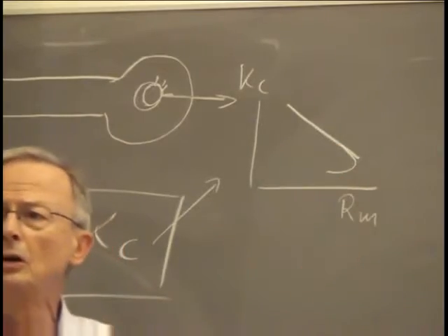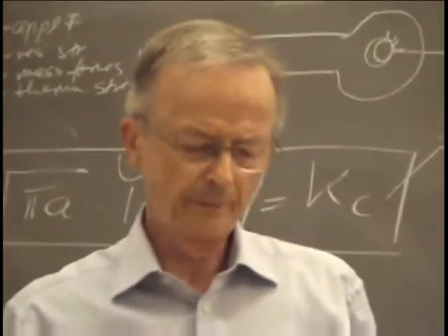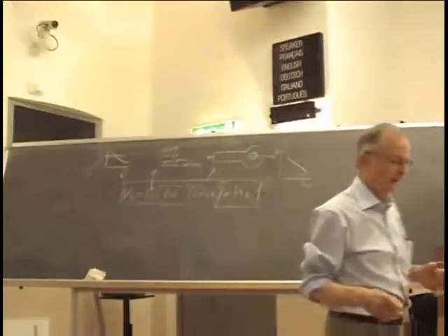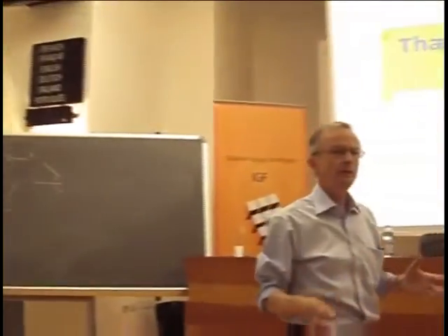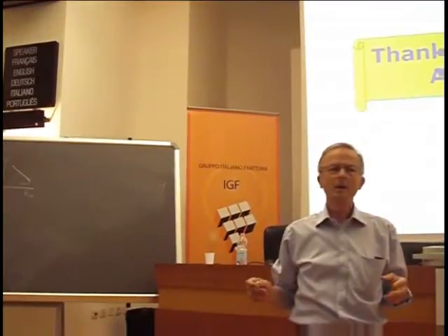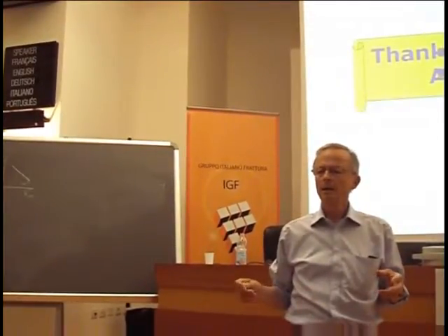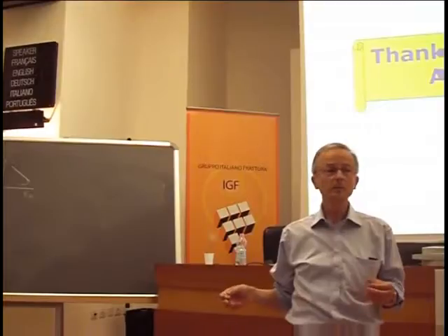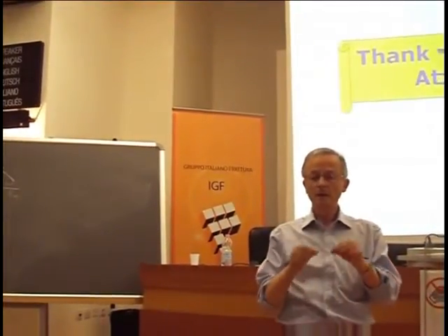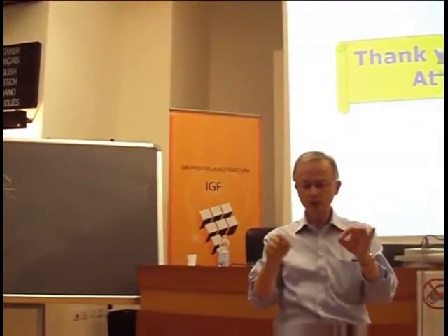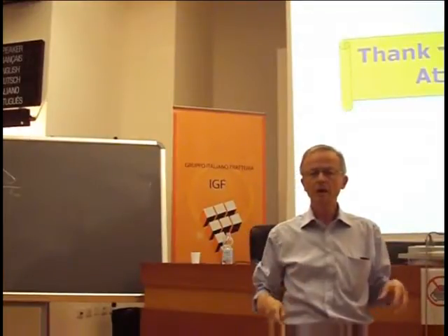No, it doesn't, because when you overage, you generate precipitates of the equilibrium phase, relatively big particles, and many of them are precipitated at grain boundaries. So you have relatively dense chains of particles which give you a fracture path of low energy.